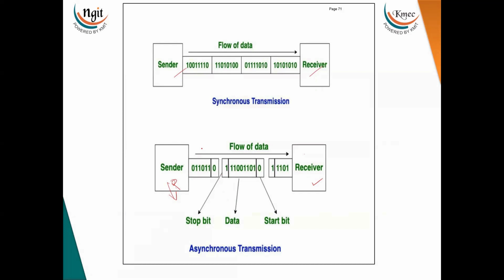And also which are connected for the asynchronous. Asynchronous means what? Both the devices will not share the same clock. So then how is the sender sending the data? It will place the data on the data bus by adding the start and stop bits.